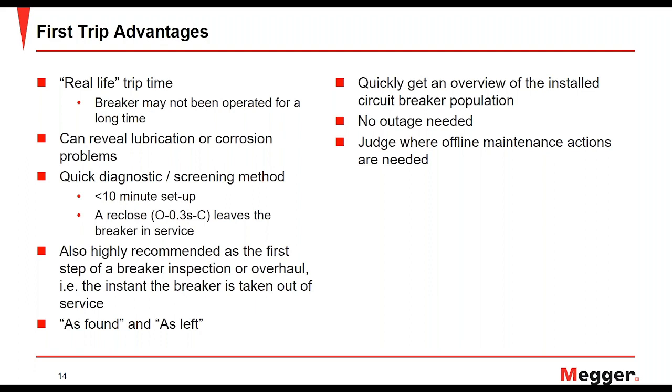You can do a reclose operation, open, close again, with this setup while it's online, and just do a quick test without requiring it to be out of service. Although, as I mentioned earlier, this needs a lot of preparation to be able to be done.